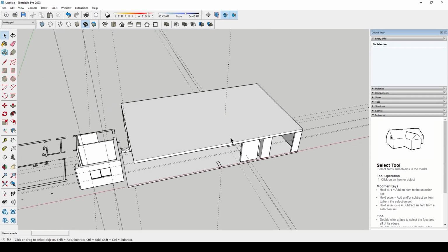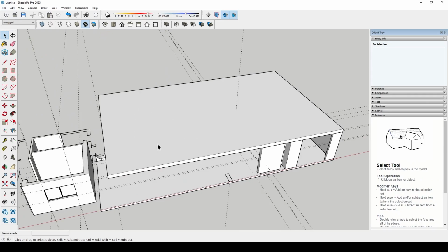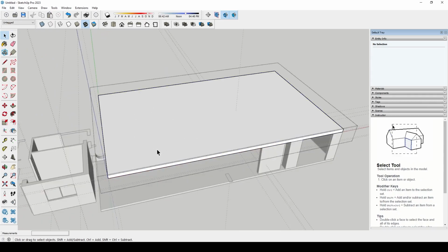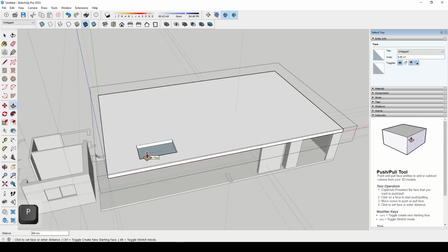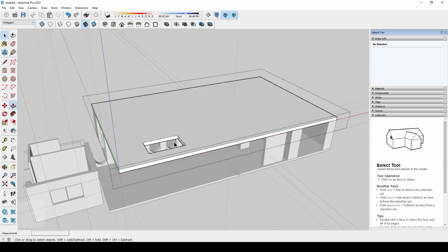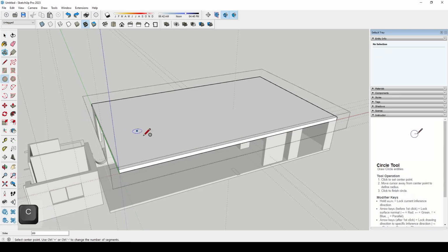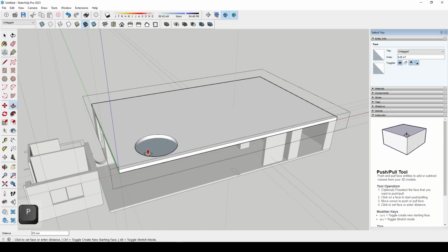Likewise, if there are holes in the slabs, we treat it exactly the same as there are holes in walls. We push it down, we go to on face, and we make holes in it. Very, very simple, very, very straightforward. Likewise, if it's a circle rather than a square hole, or if you've got an arch hole rather than a square hole, you can just go ahead and push that through. Exactly the same strategy. On face. There we go. That's it. So that is your slabs.